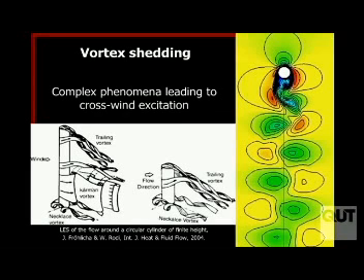So here are some examples of flow simulations around relatively tall, slender structures. You can see sheets of vortices forming. Clearly near the top there's something special going on as the flow goes over the top. But clearly we can generate, at least for long two-dimensional structures, this street of vortices behind it, the von Karman vortex street. And that alternating flow pattern leads to alternating pressures, which leads ultimately to an alternating crosswind force. And that's the one we're trying to avoid.